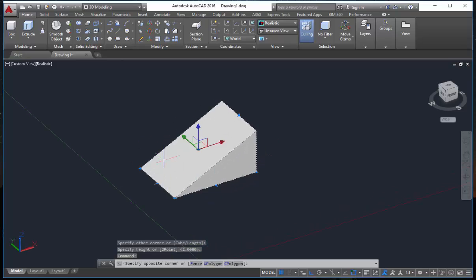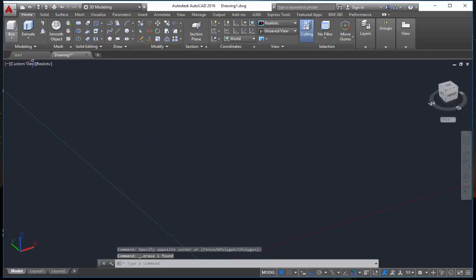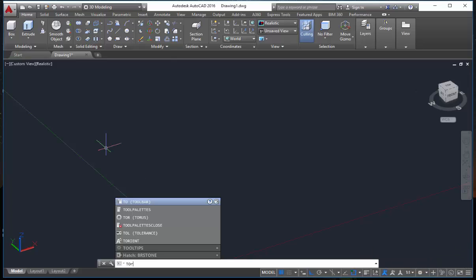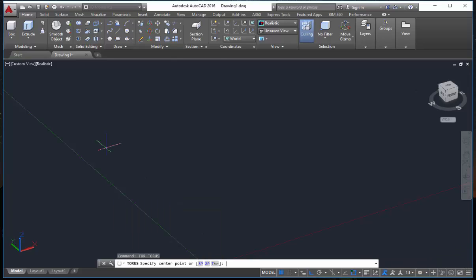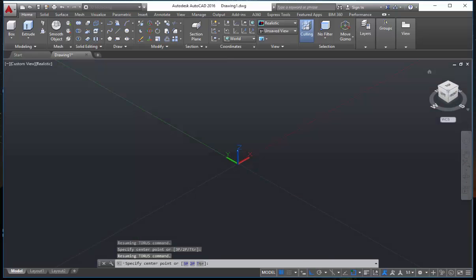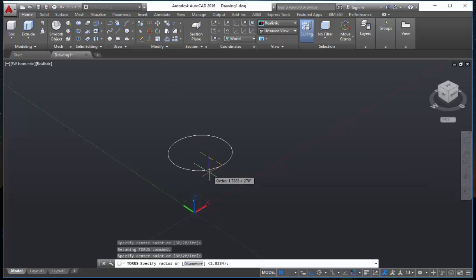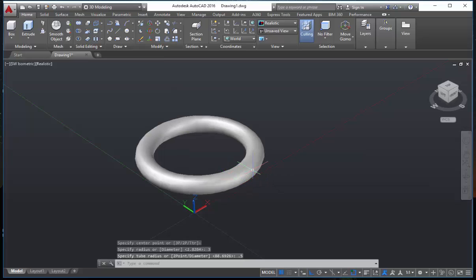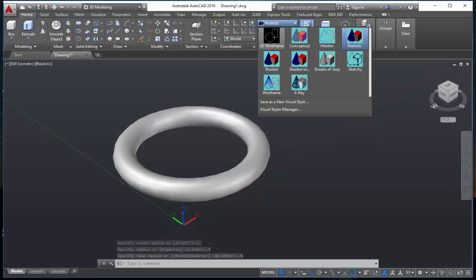So the last 3D basic object is a torus. The short key for torus is TOR, enter. Again here I am going to draw a circle, so it is asking whether you need it as 3 points, 2 points or TTR, otherwise I just specify the center, I'll give the radius as again 3, enter, and the inner radius I'll give it as 0.5. Inner radius in the sense, just make this as 5 frame and see, this is my inner radius, in the sense thickness of the pipe.